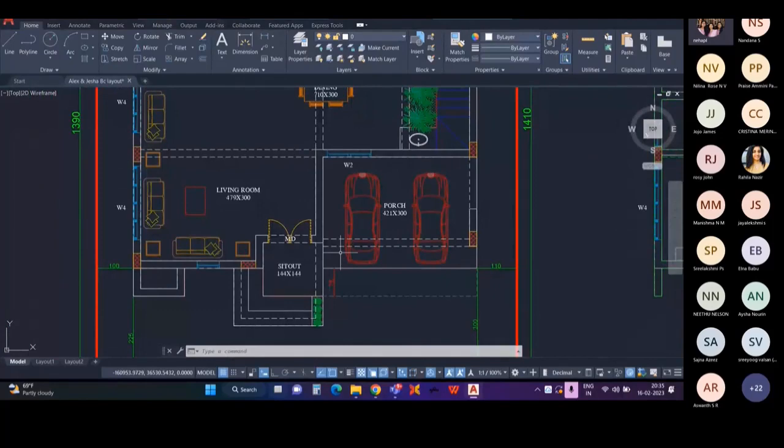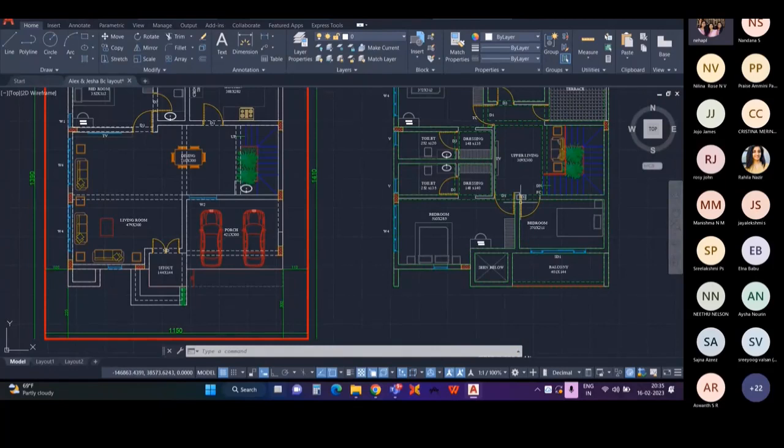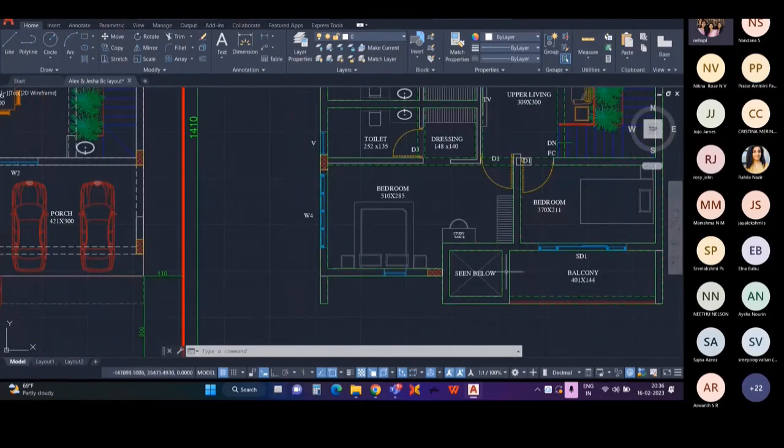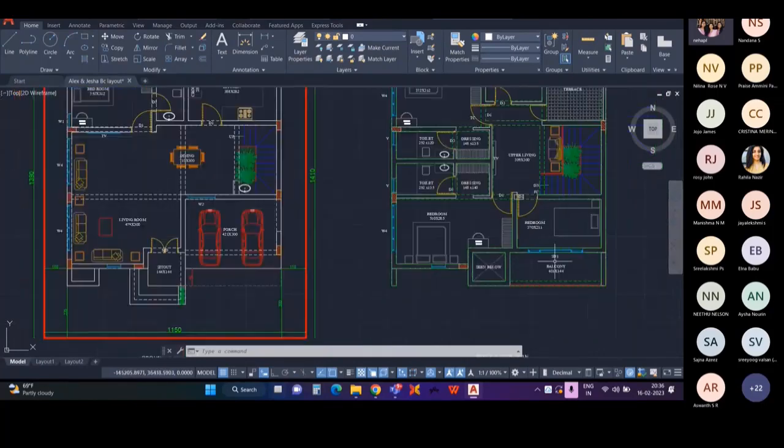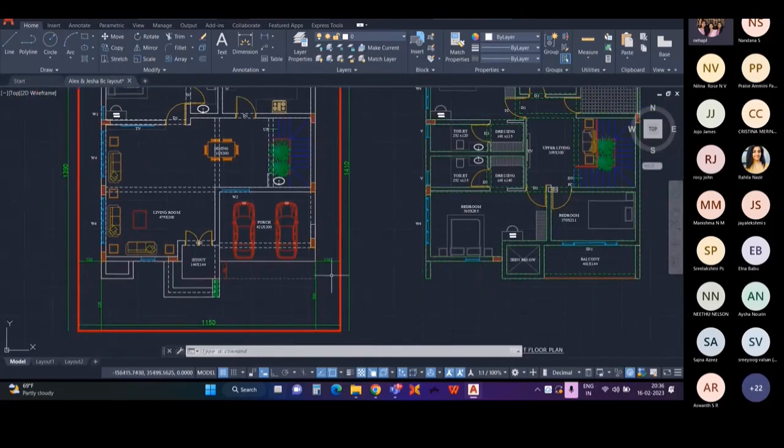After that, when we look into this portion, this is the main beam and there are beams coming into it. So this beam will become heavy and there will be a chance of deflection and failure. We need to provide a column at this portion too, because this is a long beam without column connection, without support. And there are beams entering it, so chances of deflection are higher and failure will happen. So we should provide a column at this portion too.